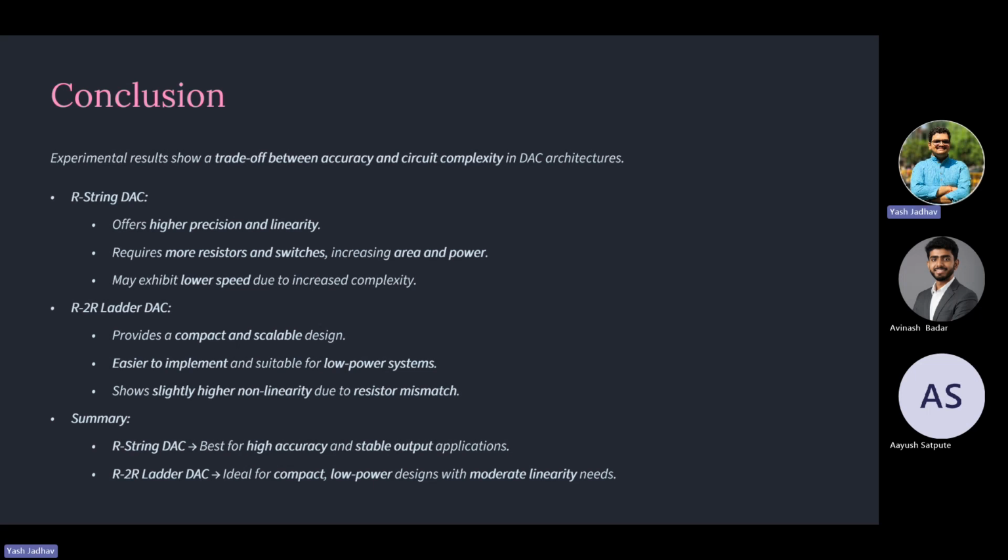In summary, we can use the R-string DAC for high accuracy applications and where power is not a factor to consider, meaning we can use a lot of power. Meanwhile, we can use the R2R ladder DAC for compact, area-based, low power applications.